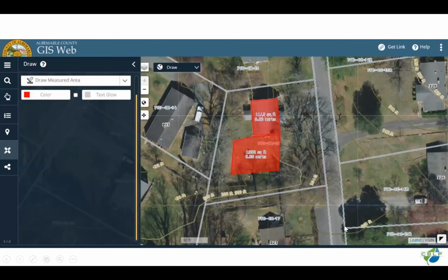But the first thing we want to ask is, what's the drainage area? This is going back to that county GIS map. Here is the house, that blob there. This blob here is the part of the yard which drains, and right there where Megan and Courtney were standing is this grass area right back here. So what's the drainage area to the potential BMP location? Well, one thing we know, it's some of the house, some of the yard.